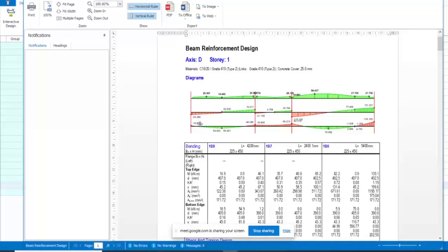But you discover that there are values at that point, meaning in the configuration of this program, there has been an allowance at that point for moment. That means there is fixity at those ends. So it will relieve the moment at the midspan, then increase it at the support.